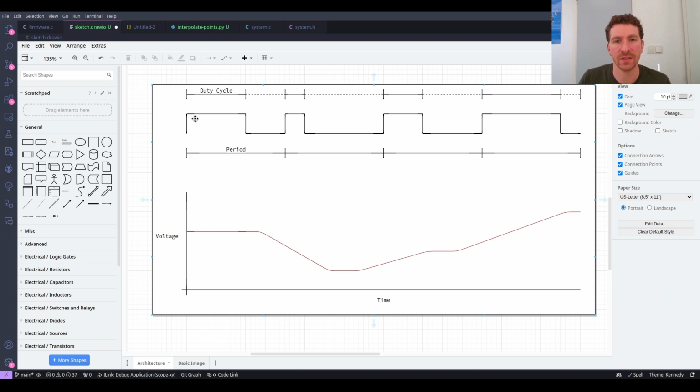So we need the low pass filter to take that out and average over many periods to grab what we're actually encoding here, which is 60% of our maximum voltage. So that's what the low pass filter does. It filters that down to that level. And so this is a rough, not quite accurate representation of how this would look once it's gone through the low pass filter.